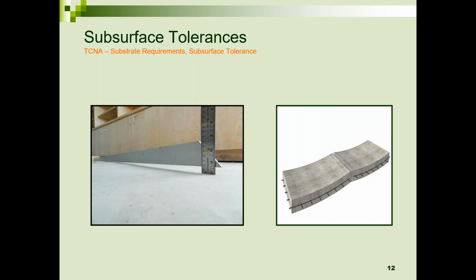So what is measured as flat 3 days after installation of the substrate is not flat when you, the tile contractor, run out to that slab for your installation. And what's more likely is what you see on the left. Look at that straight edge going from left to right. You've got a gap that's maybe a 1/2 inch, 3/4 of an inch. And I'm sure it was measured flat with an FF number 3 days afterwards.